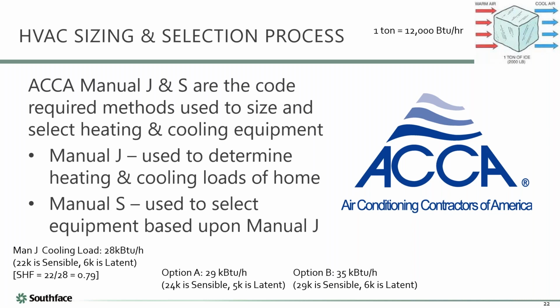But you'll notice it's also oversized by a fairly significant amount. And you can do another check to see if your equipment is oversized. I think it's 15% oversizing that you're allowed, and we might be okay on that. So we have to do 35,000 divided by 28 and see if we're more than 1.15. I think we would be oversized.